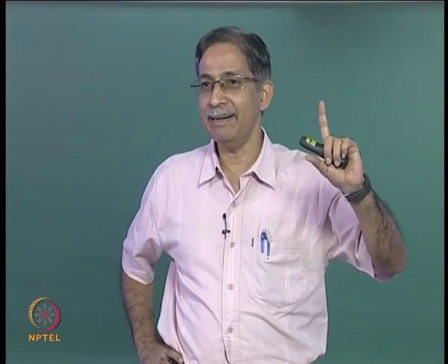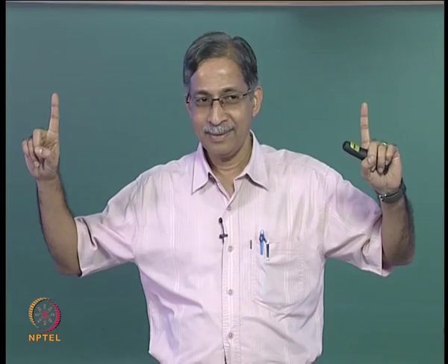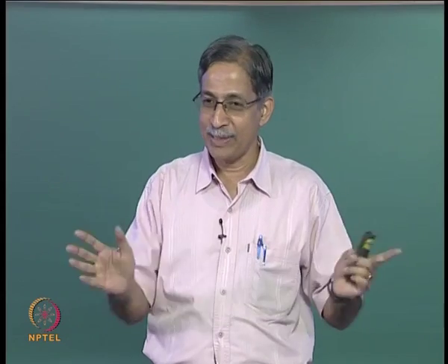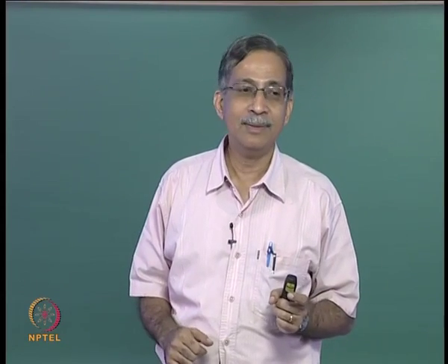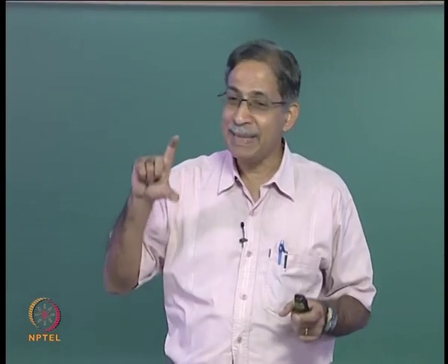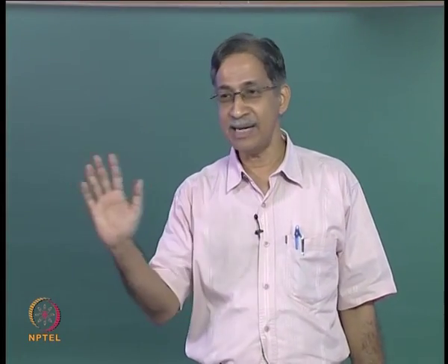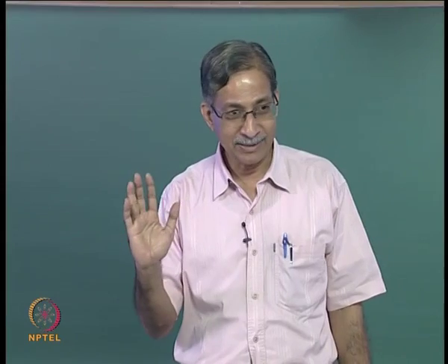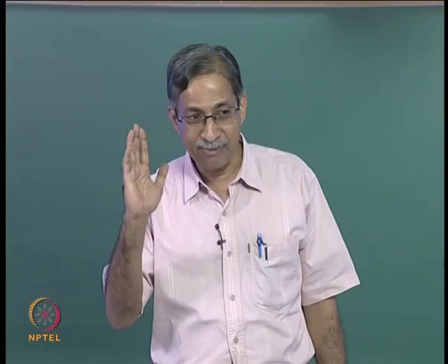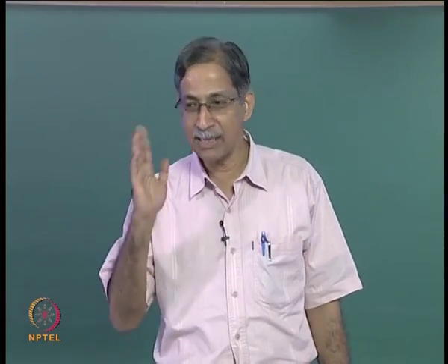Let's be very clear. This is a statically determinate beam. Your midspan moment will not always be WL by 4? Whatever you do, plus P delta is what you do in second order analysis, that is what you should say. In first order analysis, the answer will not change. Even if you had material non-linearity, it will not change. WL by 4 remains WL by 4, even if that beam yields.